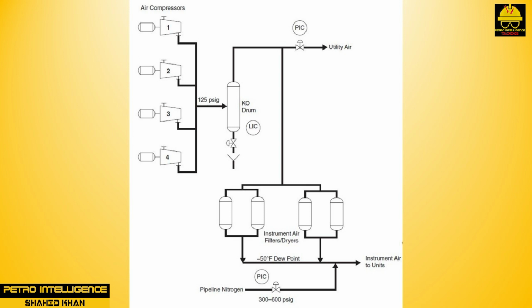The air compressors are set up to produce approximately 125 psi air pressure into the system. Because the instrument air (IA) system is the more critical system, pressure is controlled to 100 to 105 psi. Utility air (UA) has no pressure control.